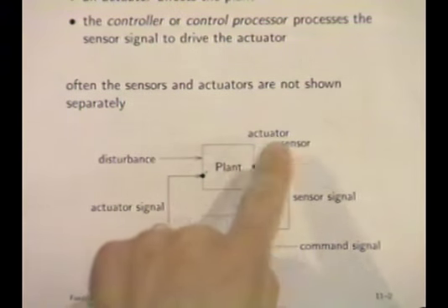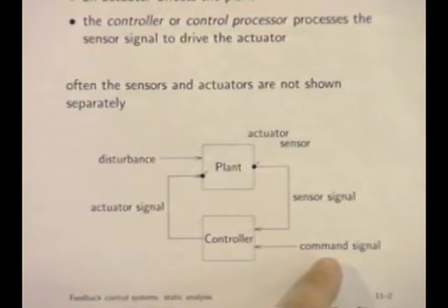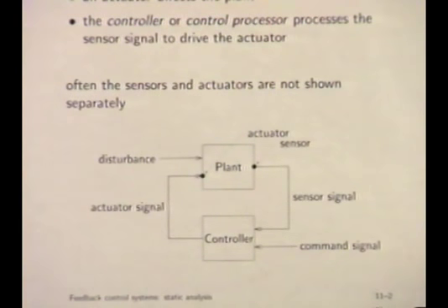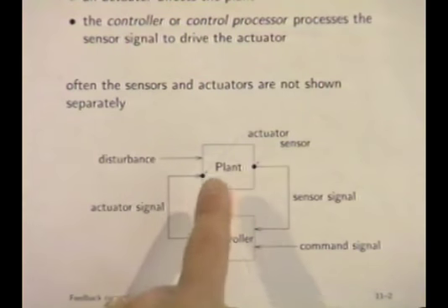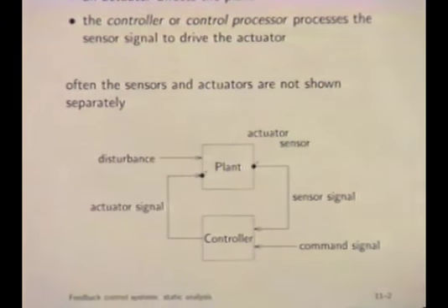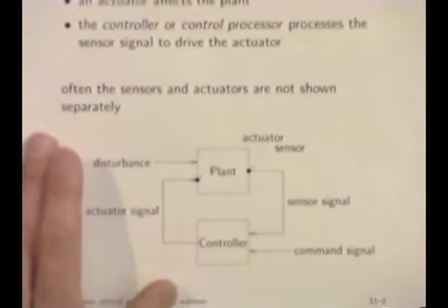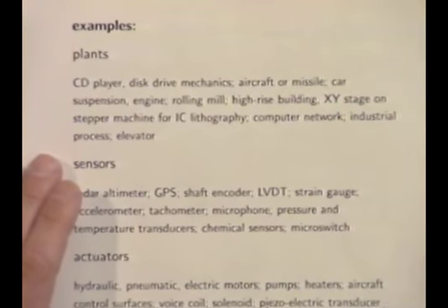Those would produce electronic signals, which would also look at the command signal. The command signal would come from an operator and say, move to the following XY position, and it would compare where it actually was with where it needs to be, and generate the correct signal to the motors to move it to that position. That all makes it sound very simple. So this is the basic idea. This is abstract, but here are some examples, and maybe this will make it clearer.